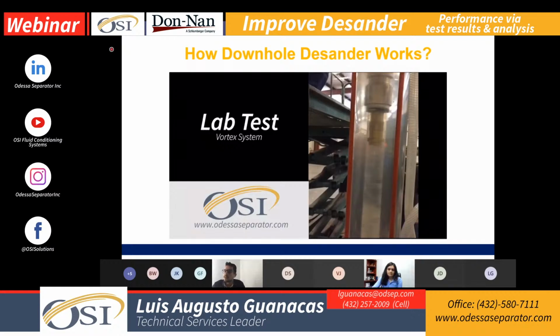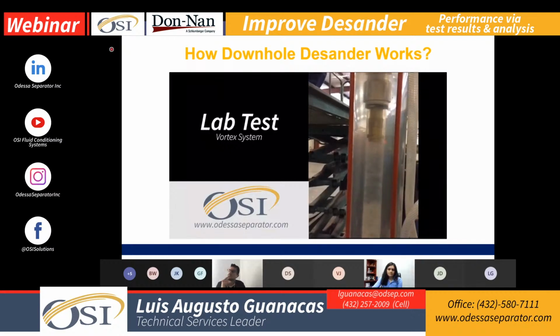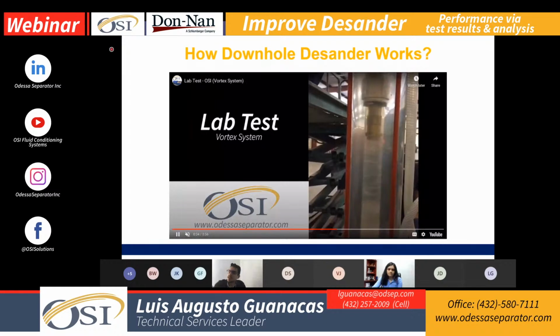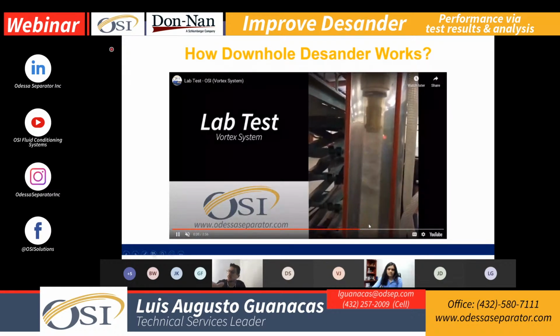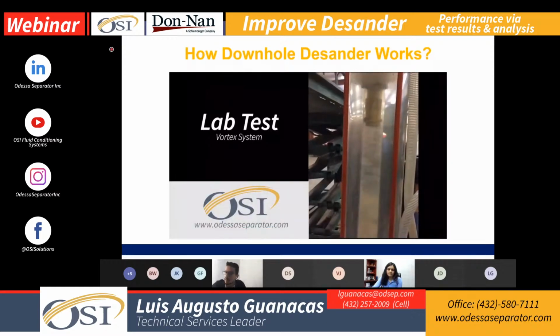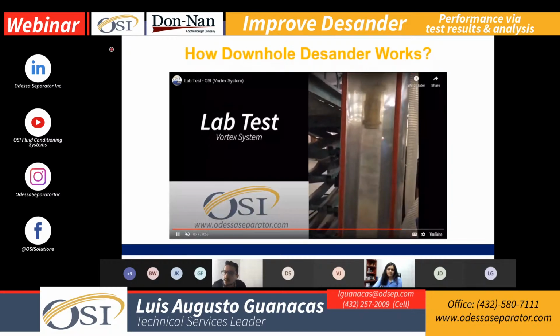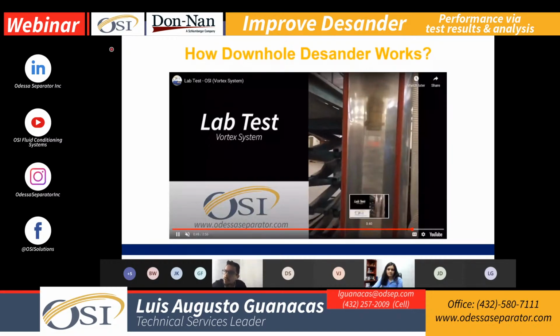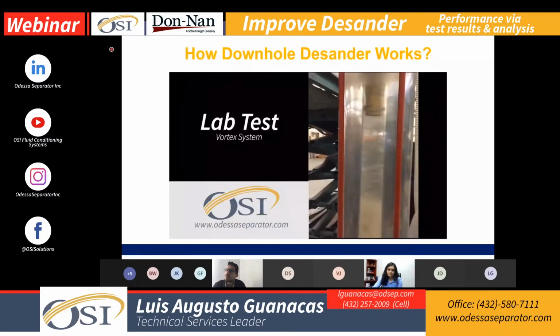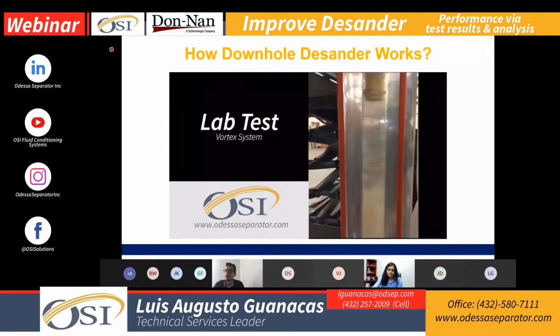the helix, it is causing this rotational movement, right? And then at the bottom, look how all the sand is being concentrated at the bottom of the tail joint. And close to the helix, close to the dip tube, you will see the vortex. Maybe it's not really clear, but you can see close to the helix the vortex phenomenon sucking the fluid inside the dip tube.